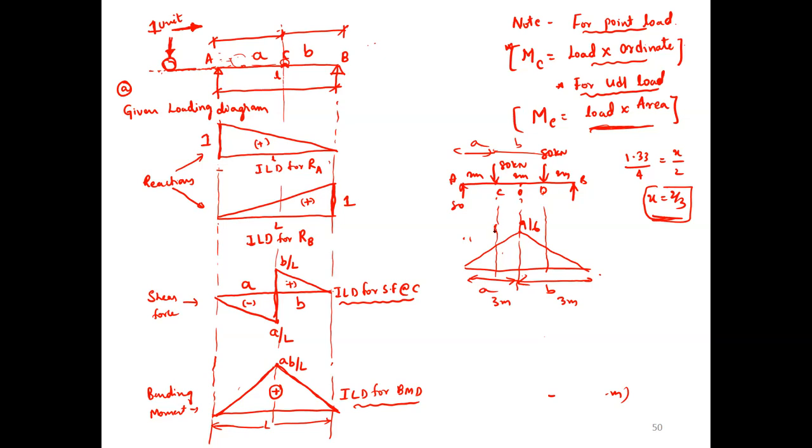But this load multiplied by this height, plus this load multiplied by this height, you are getting this. Here there is no load given, so 0 multiplied by this height is 0. This 9/16 will not be of use. Now if you want this height, consider this similar triangle, this is 9/16. What is the value of this? This total is 3 meter and this one is 2 meter. Find the height. Same height will be on this side.